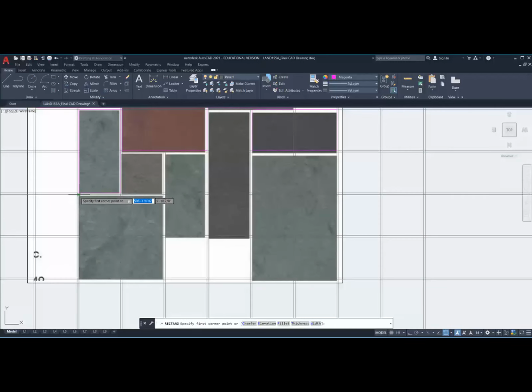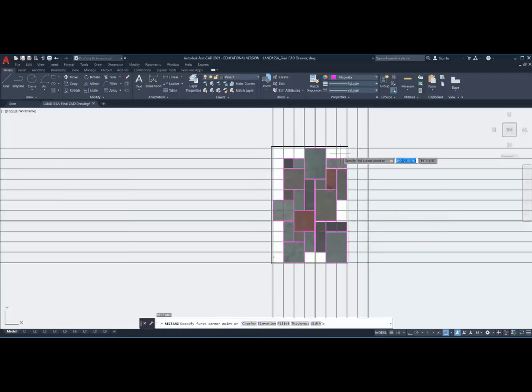Now, again, each manufacturer has a different dimension of tile, so we can't be switching between manufacturers. So one may be 6 1/4 or 6 1/8, another one may be 5 3/4 inch. So it's really tough to do a random pattern like this with multiple manufacturers, especially ones that have different grid sizes or grid spacing of individual components. So we really have to stick to one manufacturer. Now, we can have a second manufacturer doing, let's say, the borders on the outside, because they may not have a relationship to what we're doing here with the infill. So this is for the infill only.